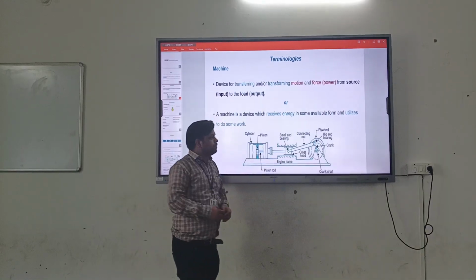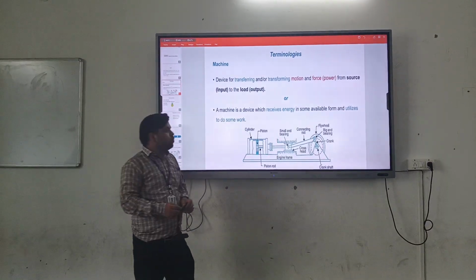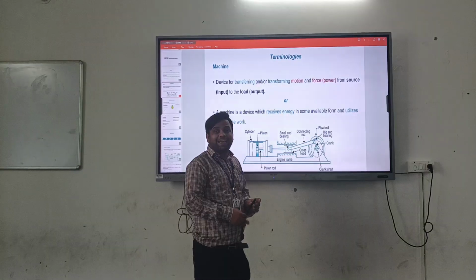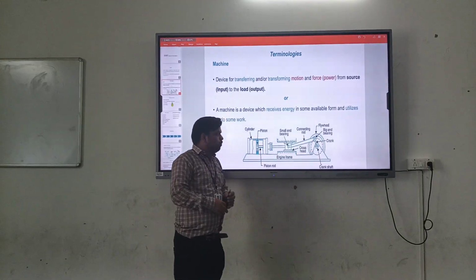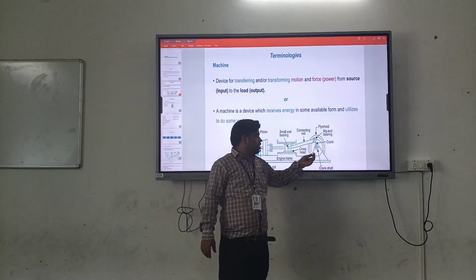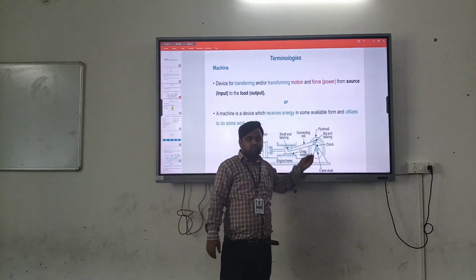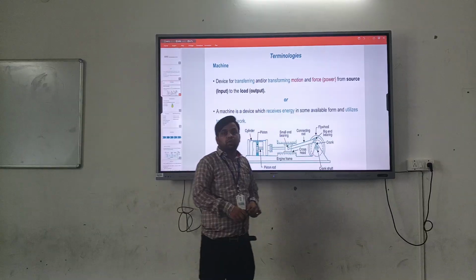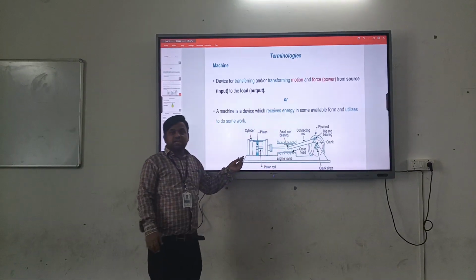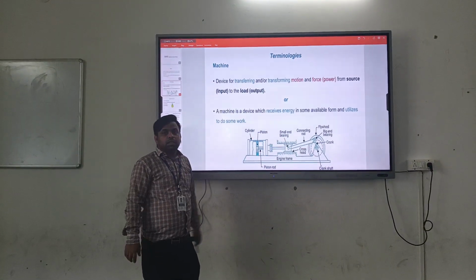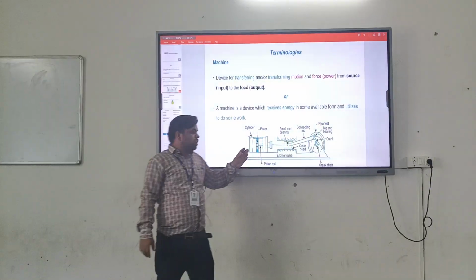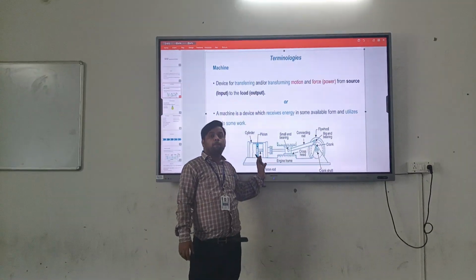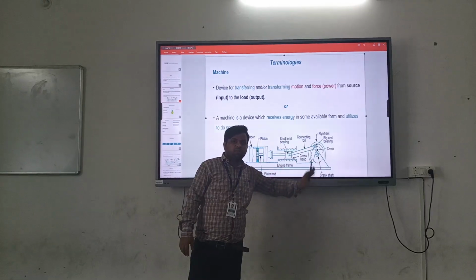The flywheel has the purpose to store the energy and reduce the vibration during the circular rotatory motion of the crank. So, in this single slider mechanism, the reciprocating motion is converted into rotatory motion.